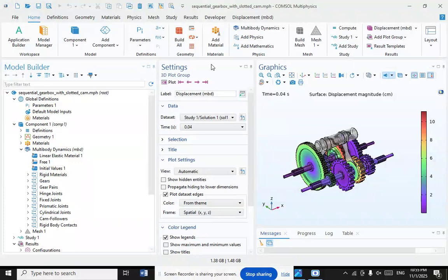When neutral is selected, none of the gears on the output shaft are locked to the shaft, allowing the input and output shafts to rotate independently. For reverse gear, an idler gear is used to reverse the direction in which the output shaft rotates. In many transmissions, the input and output shafts can be directly locked together, bypassing the countershaft to create a one-to-one gear ratio, which is referred to as direct drive.